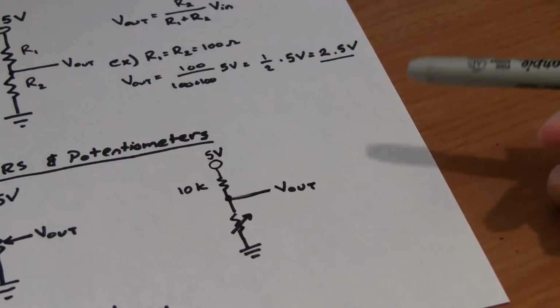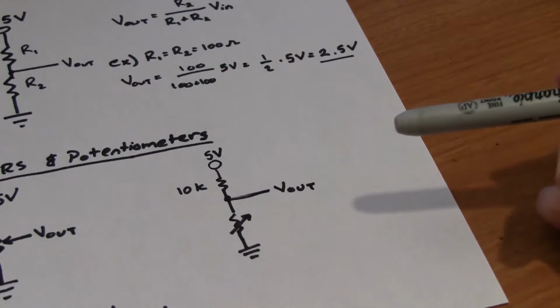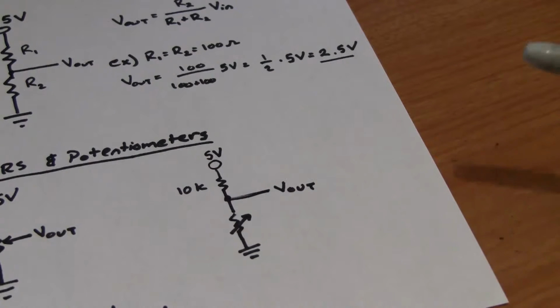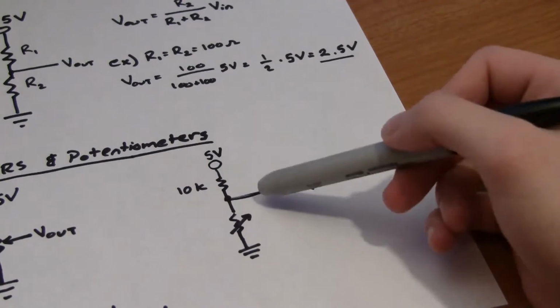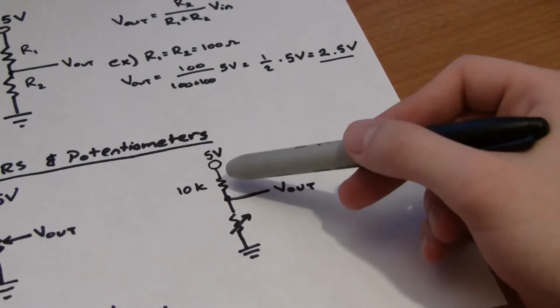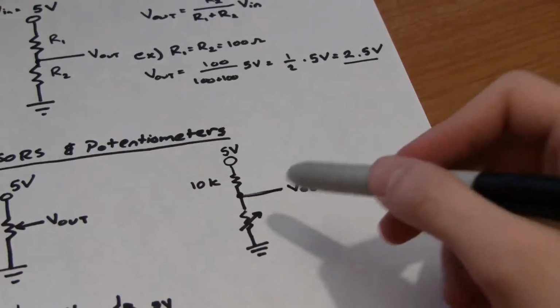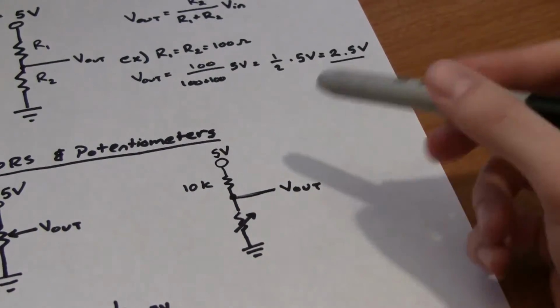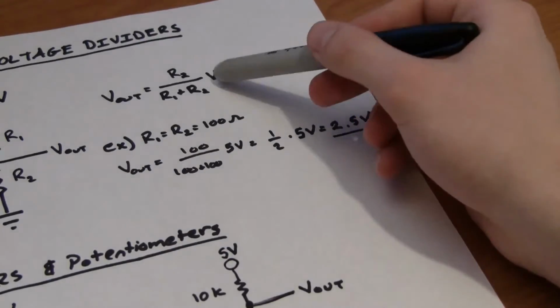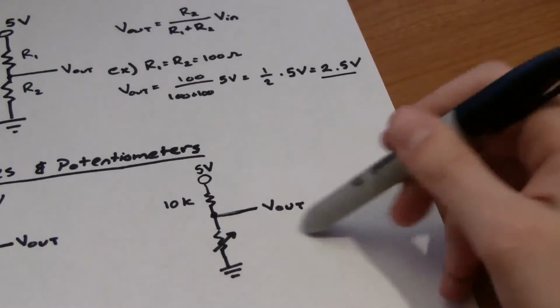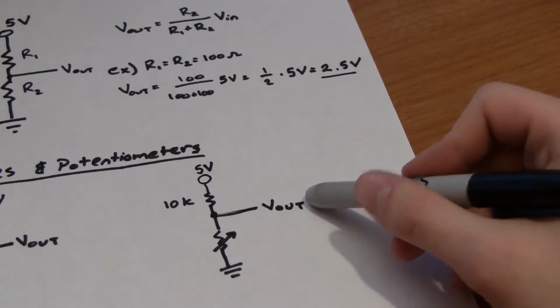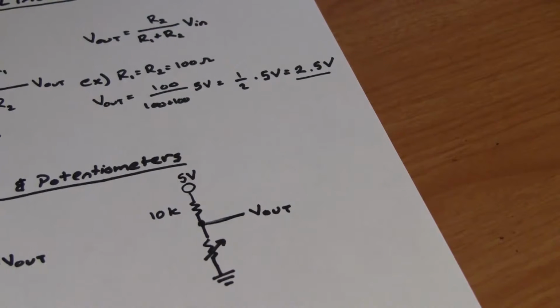Another example is when you want to hook up basically any other kind of sensor to the Arduino. Most sensors work as variable resistors. So if, for example, we have a photodiode, which changes its resistance along with changes in the amount of light in the room, which we represent like that, we can hook that up through a voltage divider circuit. So once again, we'll have 5 volts. We usually use about 10K as the other resistor, and then our variable resistor right here. So as the light in the room changes, this resistance varies, which affects the voltage divider equation, and we therefore get a different voltage out. So as the light in the room varies, we get a different voltage out of our line here, which then gets fed into the Arduino's analog inputs, and we can read that value between 0 and 5 and do something interesting as a result. So let's see an example of this in action now.